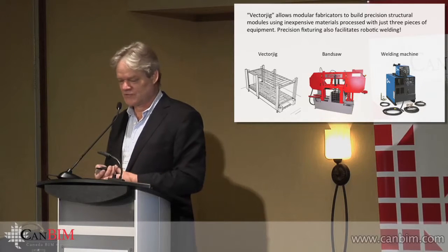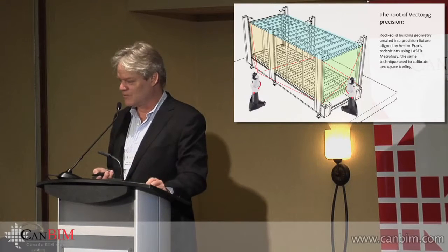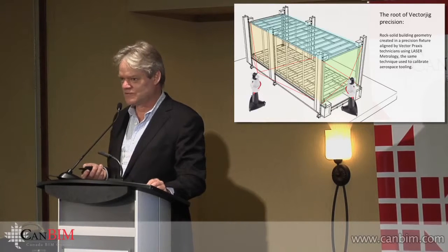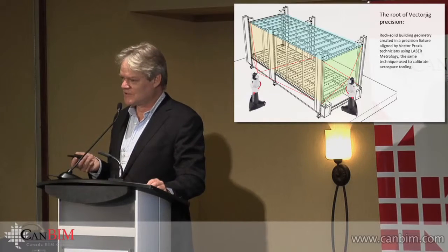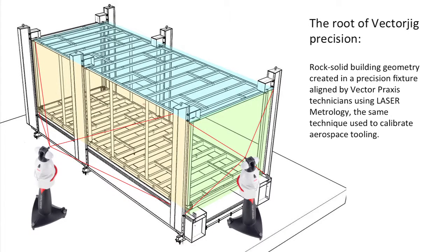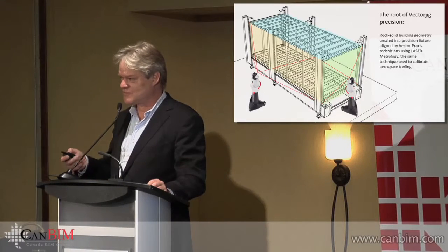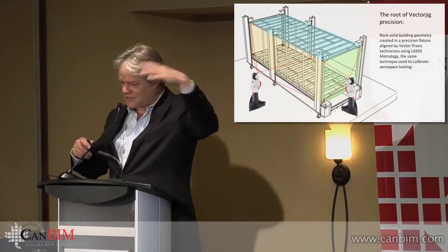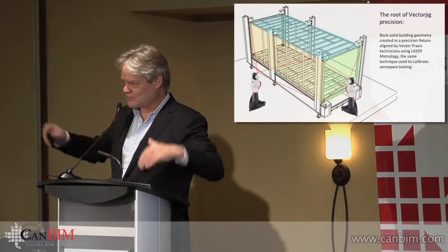The laser technology that we've been talking about is used to align something like this very much in the way that machines for industrial robotic applications are aligned. There are laser leveling systems widely available now, used by the machine tool industry, that are available on a daily rental basis, and they can measure to an accuracy of 2/10,000ths of an inch in 100 feet. These are not uncommon, surprisingly. You can generate data from those systems that will cause the heads of milling machines, of precision machines, to rise and fall and compensate for the inaccuracy that the machine has measured. So you can actually have a bent machine and produce square parts.